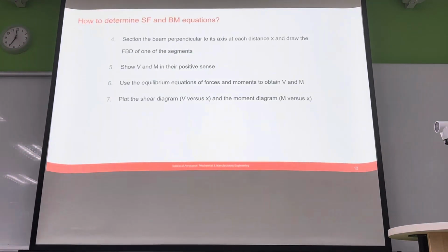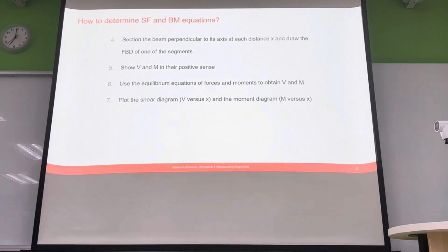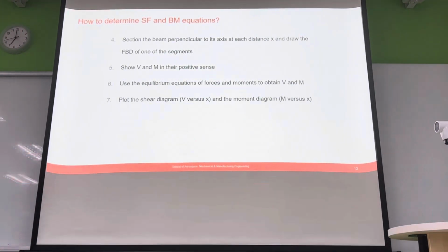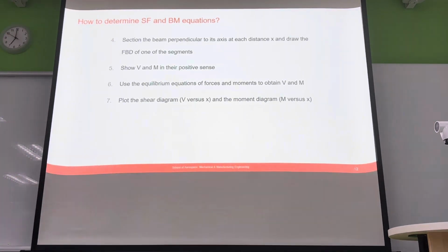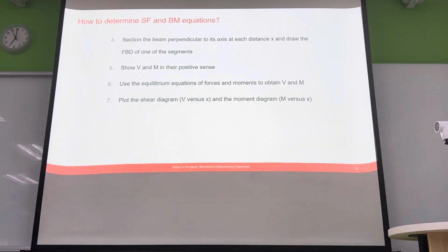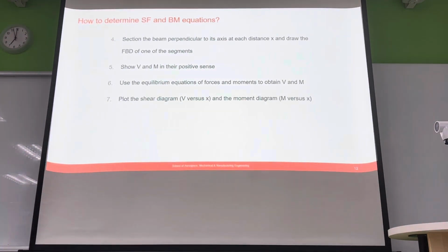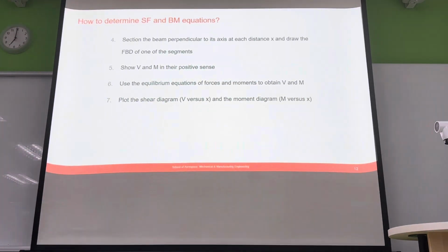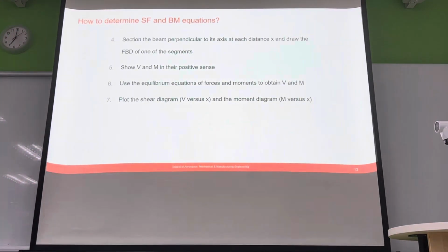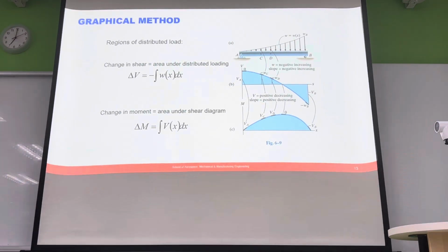Yeah, and we'll go through all that. So this is just saying that inside each one of those regions, we're going to have a relationship for the shear force, and in each one of those regions, x1, 2, or 3, we're also going to have a relationship for the moment. As I said before, we can then do sum of forces and sum of moments to figure out what the actual relationships are for V and M, and that's relatively easy. So we'll go through and do that in a second.